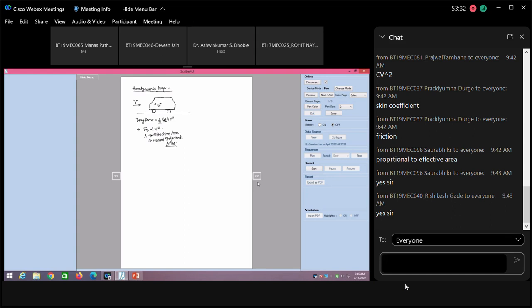So that means if you draw the graph of this with velocity, and if you see FD, the graph, there is some road resistance component. I am talking about the total. This is your road resistance RA. This is the drag force which increases with the velocity. Okay, so if I have to write down the equation, the total force of resistance is road resistance plus, let us say, your drag, which is proportional to V square. So in general I can write that it is proportional to V square, correct?